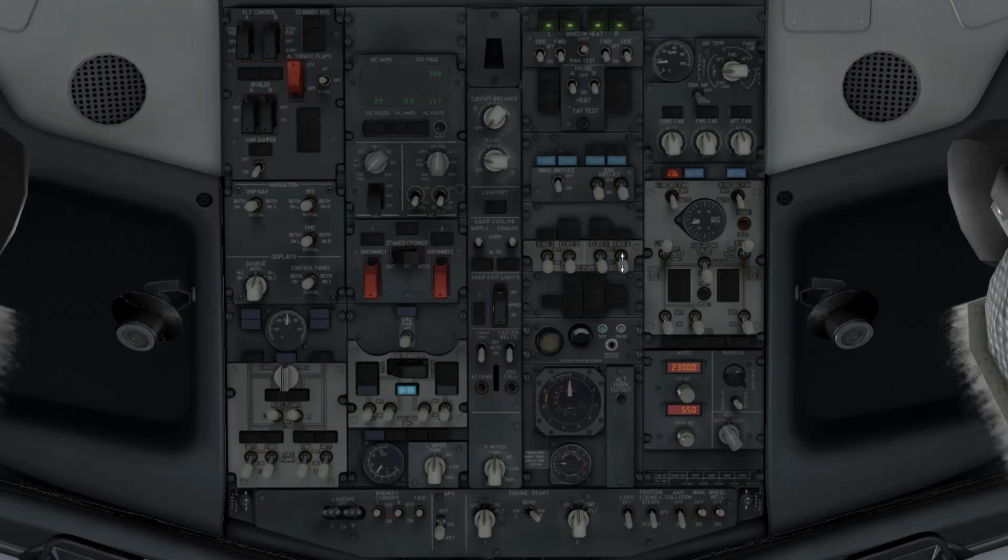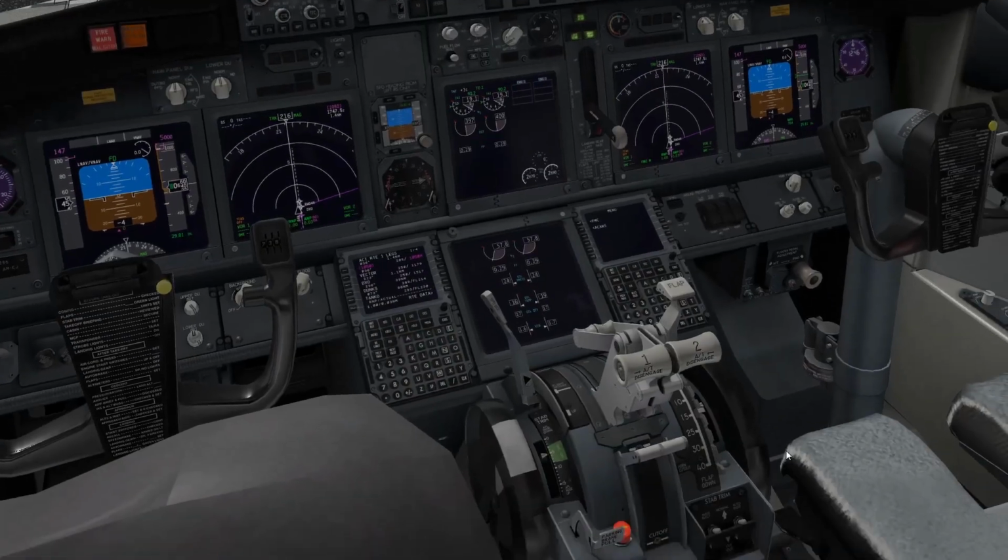All the hydraulic pumps on. Packs, they're going to go to auto. Isolation valve to auto. So it's disconnected and the bypass pin has been removed. Hand signal on the left. We'll see you next time and have a safe flight. There we go. Ramp crew's all done down there. APU bleed off. APU can come off. And flaps. Flaps will be set to 5.